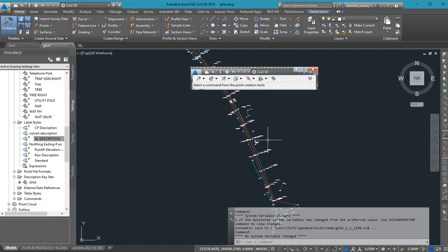It could be that because of visibility, they had to raise it, because we are only interested in the location in plan, not the elevation per se. So the points that we need to form a surface from are normally the cross sections, that's the ground levels. That is why the surveyor also picks ground levels, then the road itself. The road has a road edge, and if you also have shoulders, you include them. Shoulders, road edge, center line: both edges, the left, the right, and the center.